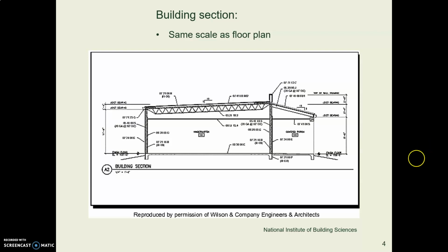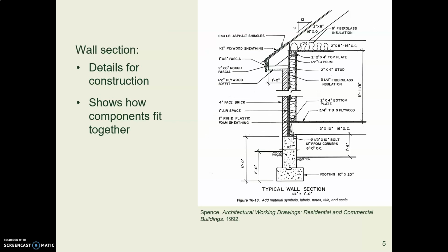This is from the National CAD Standard. They're pointing out that the building section will, if you're showing the whole building, be the same scale as your floor plan so that your reader can easily relate the two.